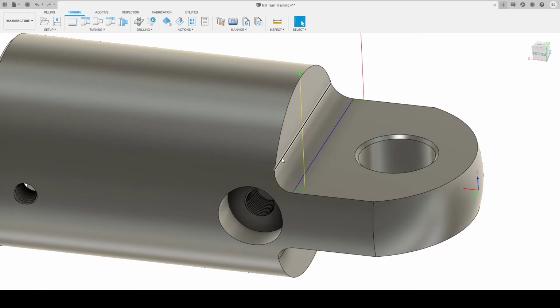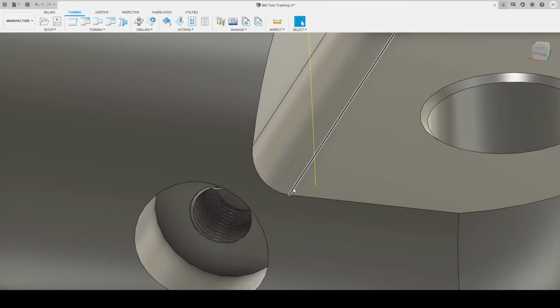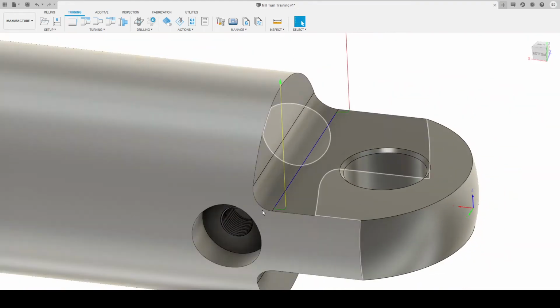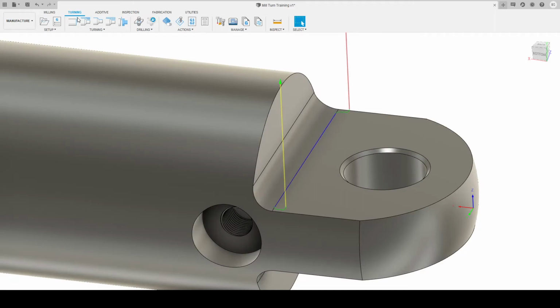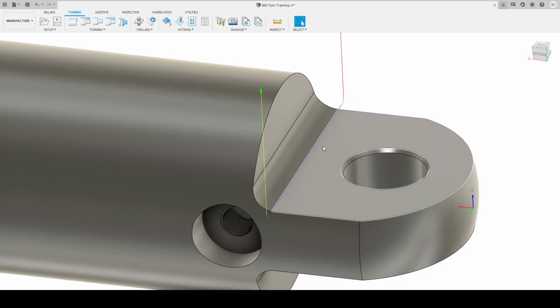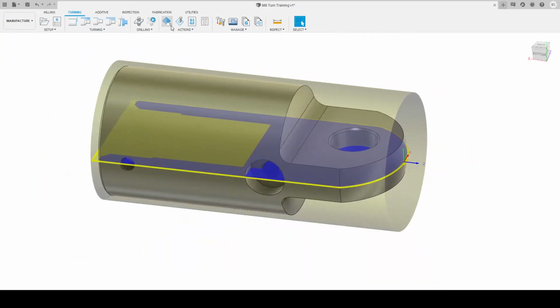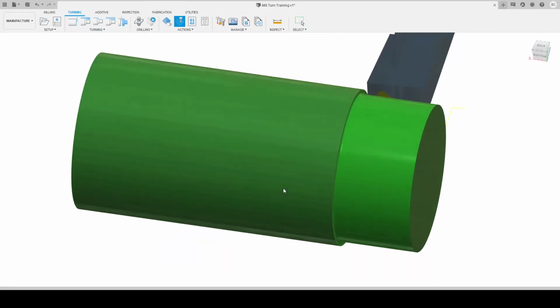Except because we've selected this contour, it's not actually going off the part. So again, edit that, and we'll go into our geometry tab and just throw a tangential extension in here, so 5mm. Again, we can change our lead in, our linking tab, change that to 0, and then OK. We'll get a straight lead in. Alright, we'll simulate all that. Let's see how we're looking.